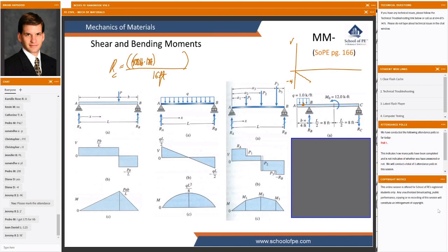And that's trying to spin us clockwise, so we're going to call that positive. Anything else go in this equation? We have reaction B at 16 feet. We've got that accounted for. We have an applied moment of 12,000 pound-feet. So we just throw that applied moment in there. And is that positive or negative? Well, if we use positive clockwise for the first one, we better use positive counterclockwise for this one.